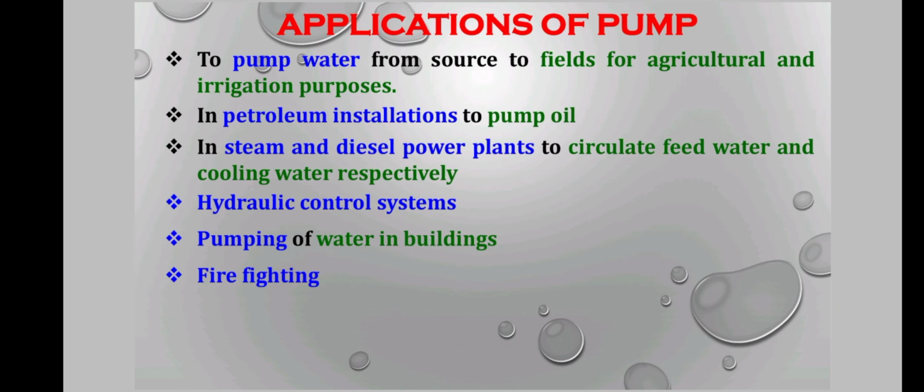The applications of the pump: pumping water from a source to the fields for agricultural and irrigation purposes, in petroleum installations to pump oil, in steam and diesel power plants to circulate feed water and cooling water respectively, hydraulic control systems, pumping of water in buildings, and firefighting.